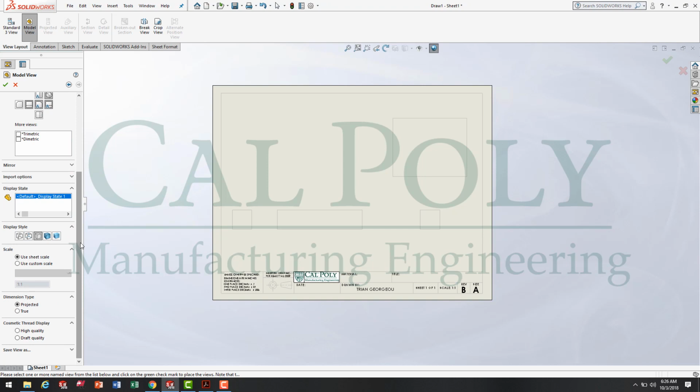Moving down a little bit, the display state is the types of lines that the CAD system will show for each drawing view. It will show full wireframe or visible, which does not contain hidden lines. It shows visible and hidden lines, or just visible lines. The other 2 are shaded models, which aren't really used on an engineering drawing, 2D. They might be used for other elements in the design process. So what we're going to select is visible and hidden lines,